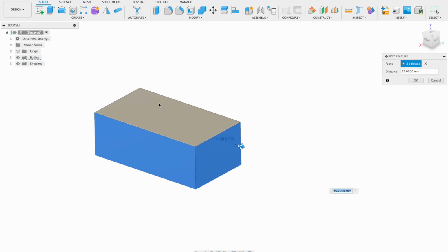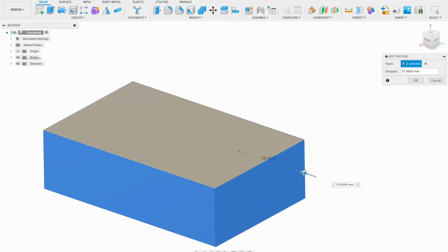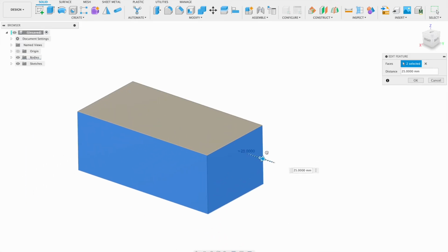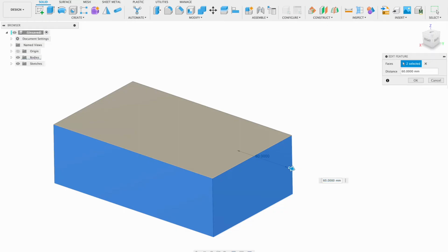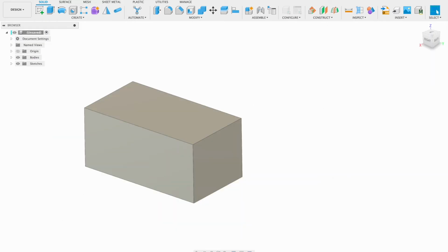This is important to keep in mind because if you apply multiple press and pulls, you might get distracted. You might lose where you were. Okay, so be careful when applying press pull. It's good to adjust a single surface because the history is there, but multiple surfaces on the same object might cause you to lose the timeline.